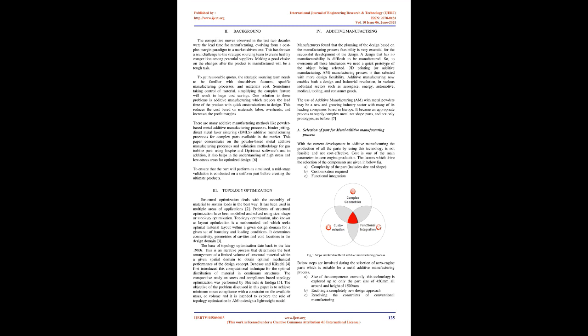Selection of part for the metal additive manufacturing process. With the current development in additive manufacturing, the production of all the parts by using this technology is not feasible and not cost-effective. Cost is one of the main parameters in aero engine production. The factors which drive the selection of the components are given in the below figure. A. Complexity of the part, including size and shape. B. Customization required. C. Functional integration.